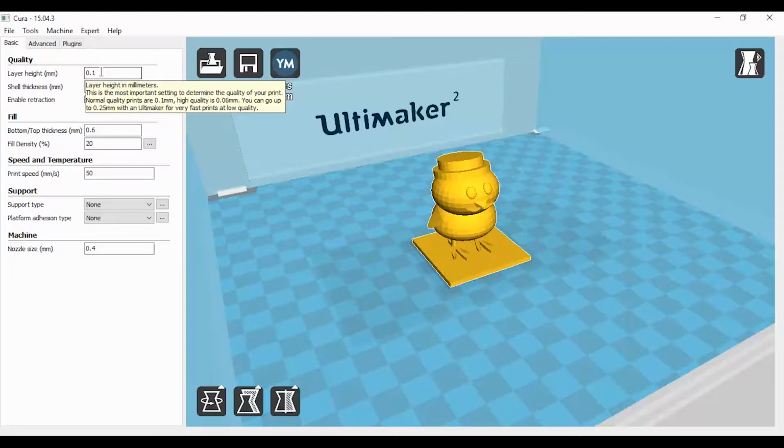So let's get started. Layer height is going to be the actual height of each pass of material the nozzle deposits. Typically, 1/10 of a millimeter is fine. For much higher quality, you're able to go 60 thousandths of a millimeter. Now moving on, the next setting is titled Shell Thickness. This is the outside thickness of your part in the horizontal plane. More or less this is going to determine how strong the exterior portion of your part will be, and when set with the layer height, decides how many passes are needed for each external portion of your piece.